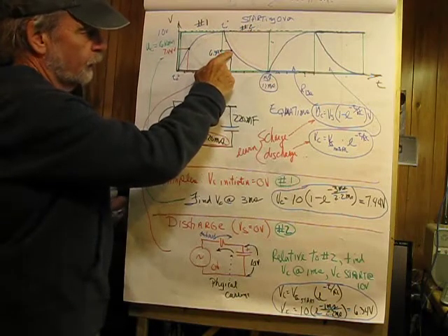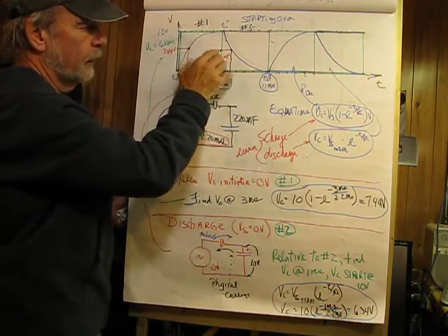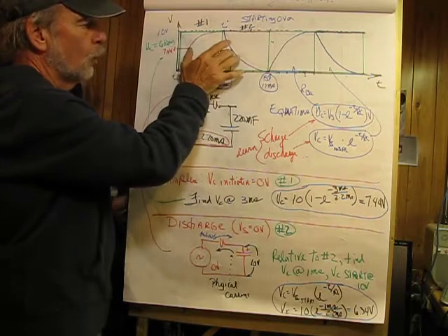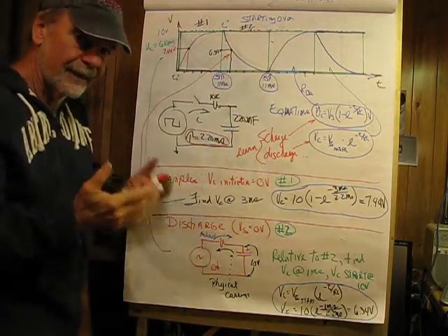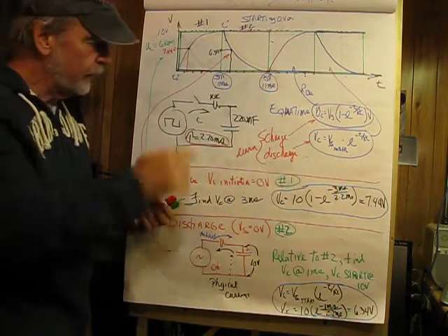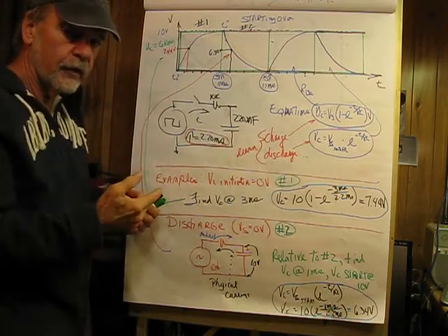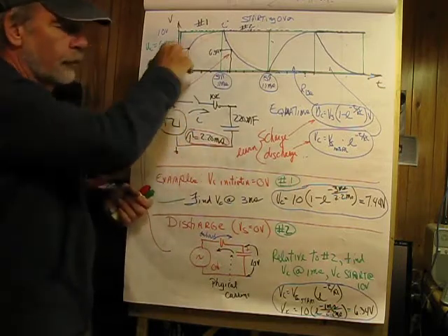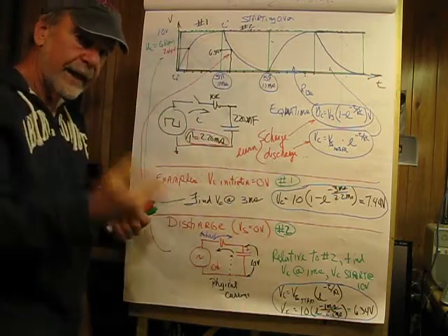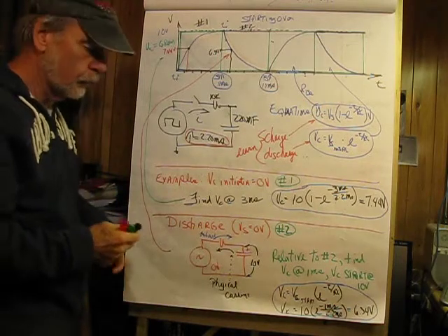So these two equations allow us to find VC at any point in time, and the reason we might want to do that is if we're interested in designing a clock. We can't have a threshold where it upticks a second. We need 2 points, so a noise burst here won't cause the clock to gain time. That's called hysteresis.